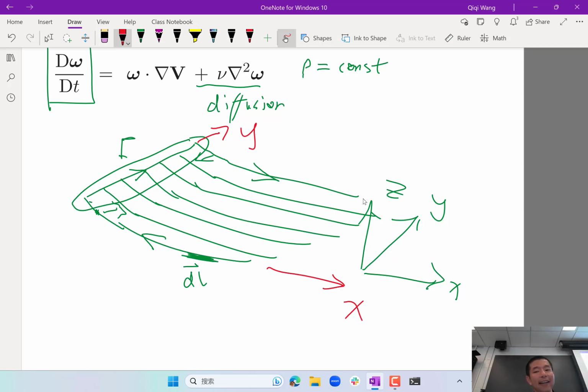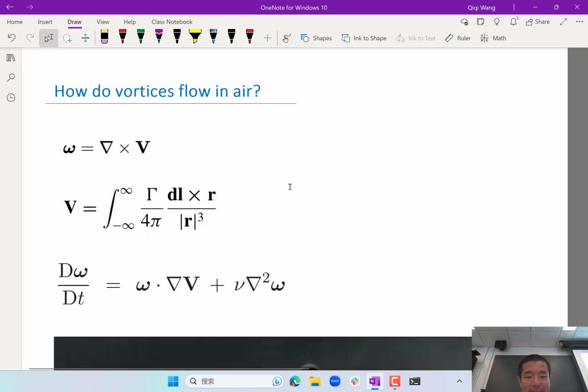Okay, so think about this, right? If the induced velocity from the bound vortex goes down, and the induced velocity from the trailing vortices goes inboard, then what is the direction of the tip vortices when they first emanate from the tip of the wing? If this is the direction of travel, it is going to go down and go inward, right, before it turns straight downstream. Let's look at some videos and see if this is actually happening.